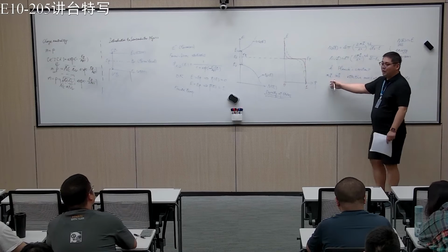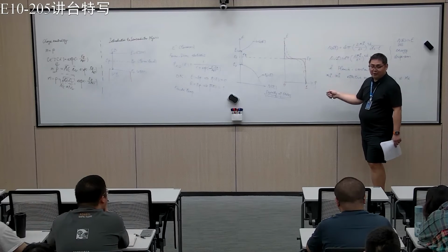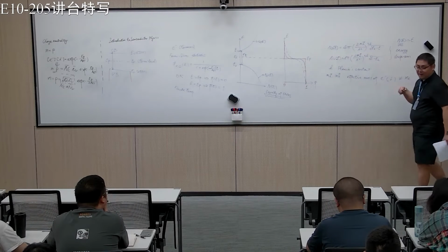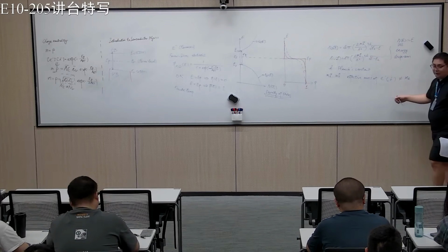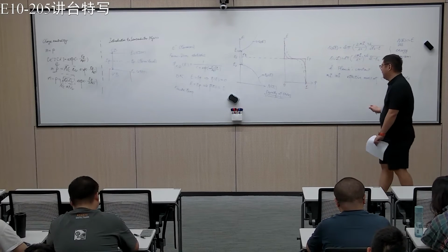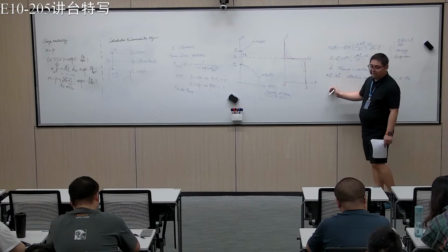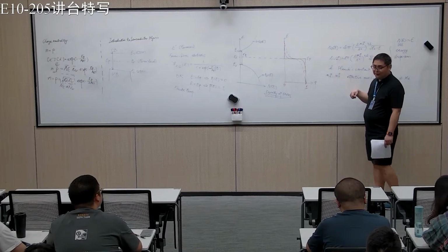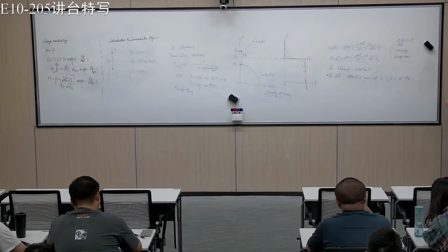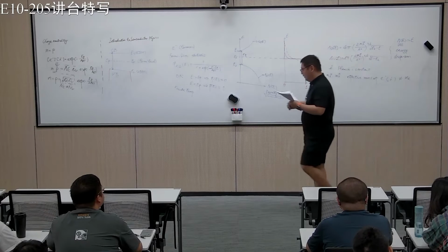But when you move the electron in the band, you have this Me star and MH star. So these are effective masses of electrons and holes. This is basically an evaluation of how fast electrons or holes can move in the band. Okay. So then things become interesting.